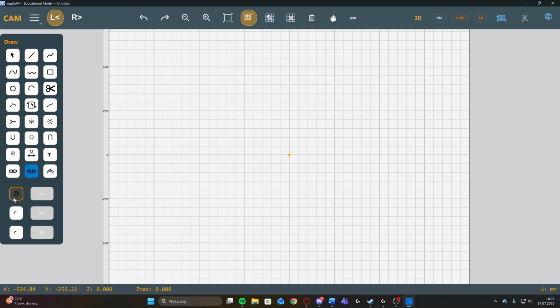Next function is going to be this one. So let's draw a rectangle. Okay, we have some rectangle. You can select the distance. So let's say 20. Okay, and when you press on it, it's going to create another rectangle like that. If you want to go to another side, you just have to have minus before it, and now it's going to go in the middle.